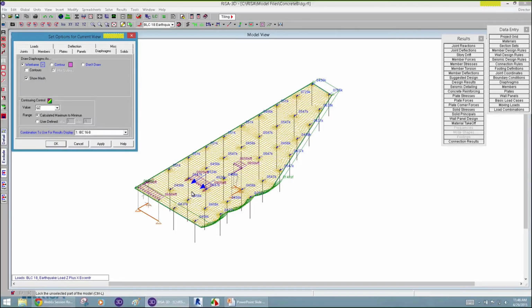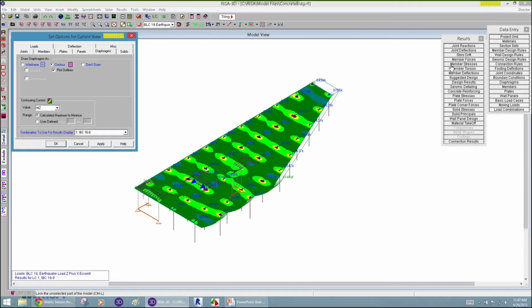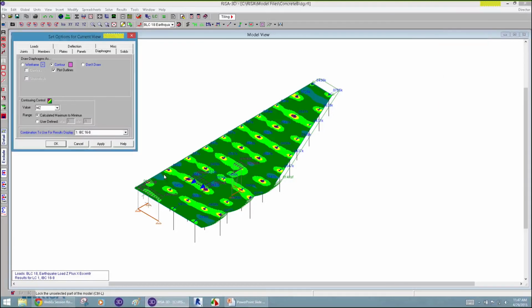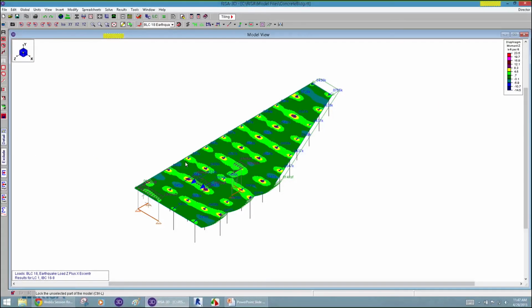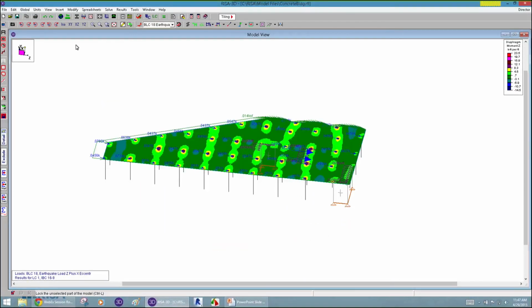So there are plates just like we did in the Risa 3D on its own. But you'll notice it's all submeshed, done for you automatically to the locations, the control points that you need, the column tops, all that is already submeshed for you. And so that's happening behind the scenes. But what you can look at is the contours. And you can see here, under these contours, we have a global direction MX and MZ. So if you were going to actually do reinforcement for lateral design, you could do it this way by looking at this. Probably that's less common, but you could, if you needed to, look at the stresses in the moments.